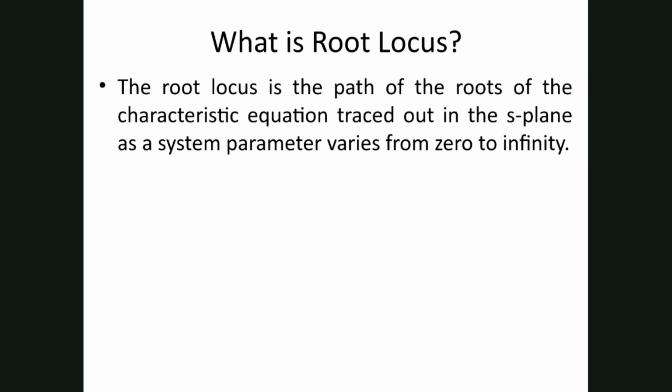Root locus is nothing but a method which gives us a kind of graph, or you can say the locus of the poles, and poles are nothing but the roots of the denominator, or the roots of the characteristic equation, in the S plane as we vary gain k from 0 to infinity. You got it? What is the definition of root locus?